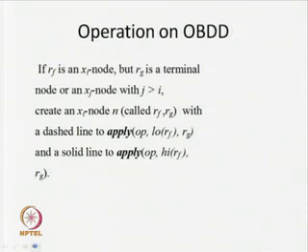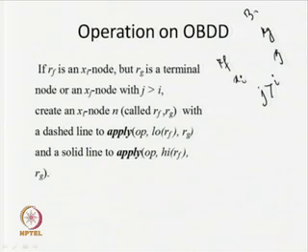So, in this particular case, say RF is having an xi node and RG is having an xj node, where say j is greater than i. While we are traversing from top to bottom, when we come to this particular scenario, one is xi and one is xj and j is greater than i. Basically, it says that this particular BDD Bg will be independent of this particular variable xi on that computation part,